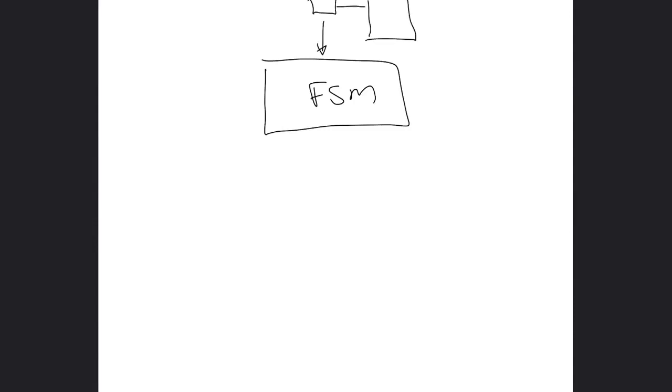There's output logic, which may be as simple as a wire, nothing fancy, and there's next state logic. The next state logic is just a simple sum of products type solution that looks something like that. That's a horrible OR gate, but that's all there is to it. You just have to figure out what that sum of products is. And on the output side, there's some logic as well.